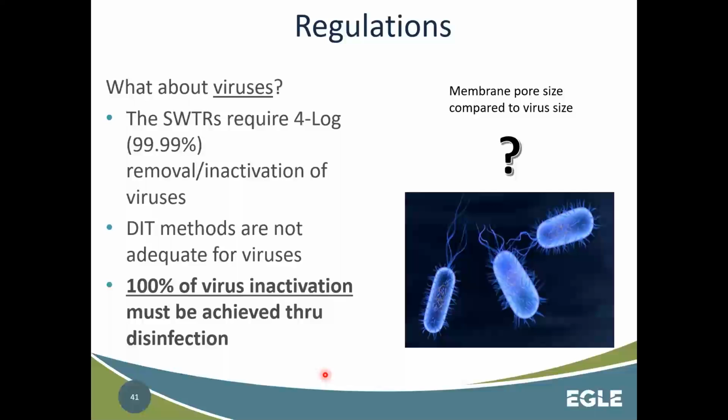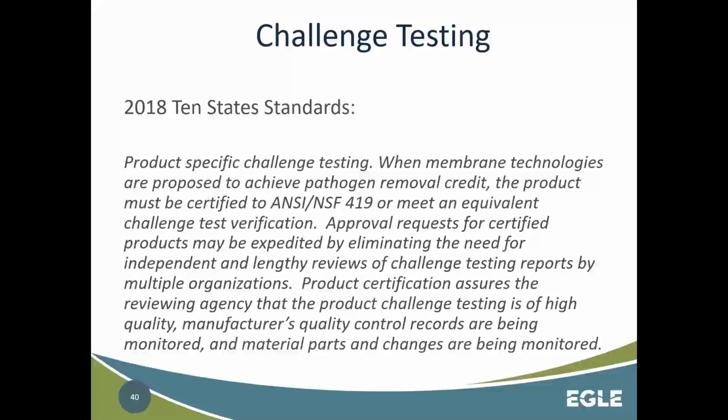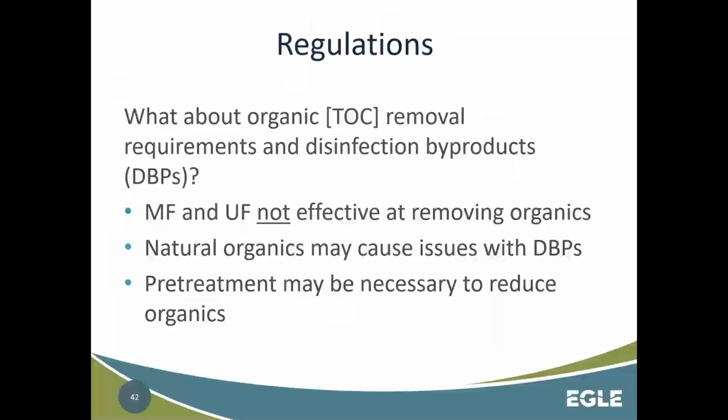And so 100% of your virus inactivation must be achieved through disinfection. But that's not that big of a deal because viruses are very sensitive to disinfectants like chlorine. So to get that CT credit for viruses is not very difficult, a small amount of detention time. So I just want to point that out. It's challenge testing. I'm just going to skip that in the interest of time.